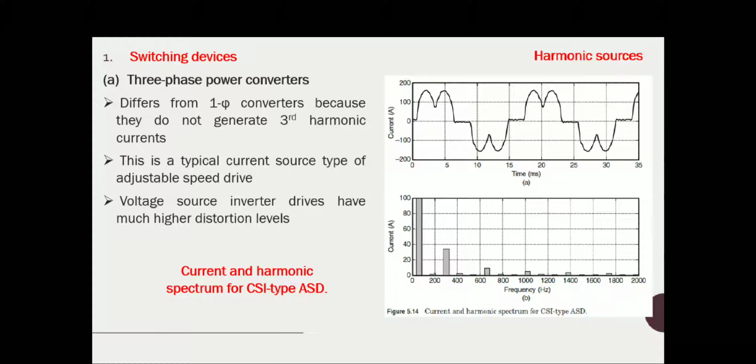So the application of power factor correction capacitors can itself potentially magnify the harmonic current from the nonlinear loads. That may lead to resonant conditions, etc. So there are a lot of adverse effects even when we are connecting a capacitor in order to improve the power factor.